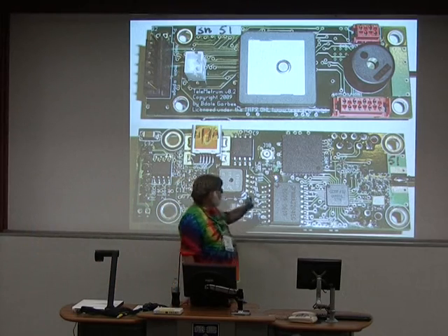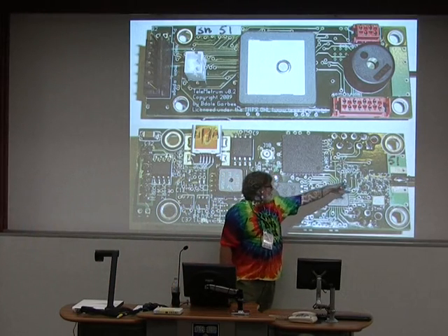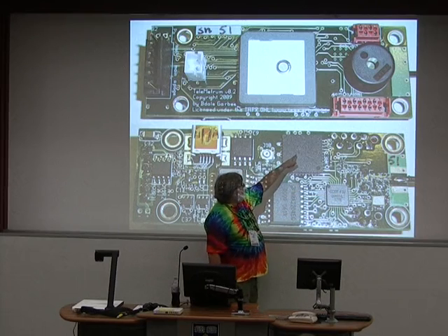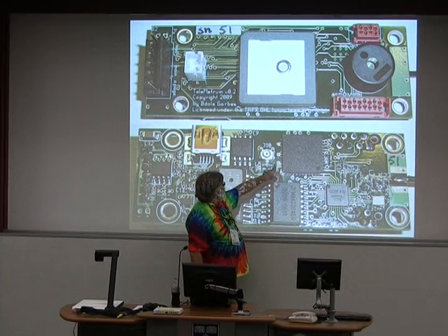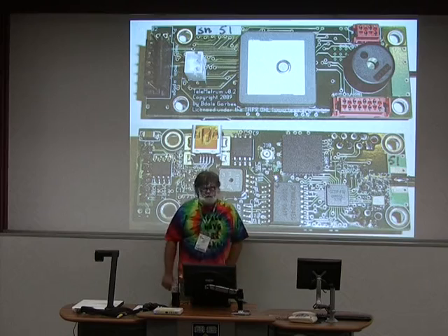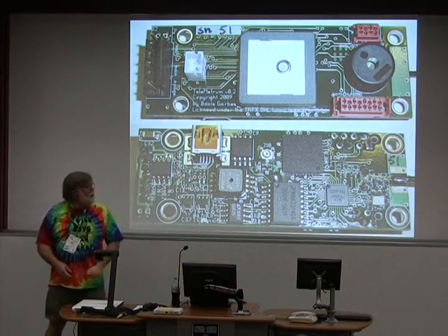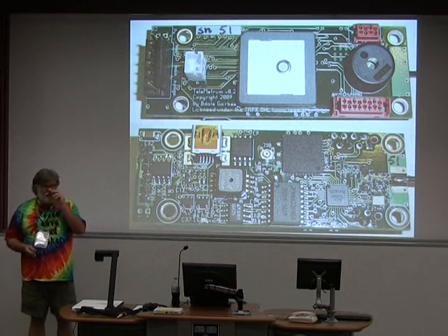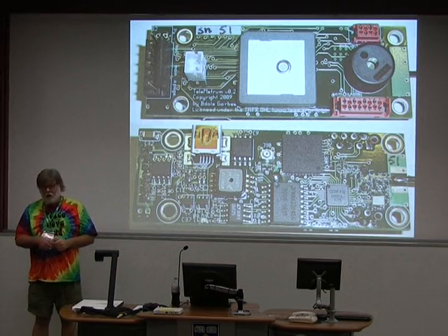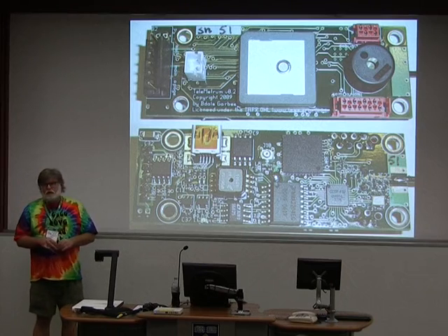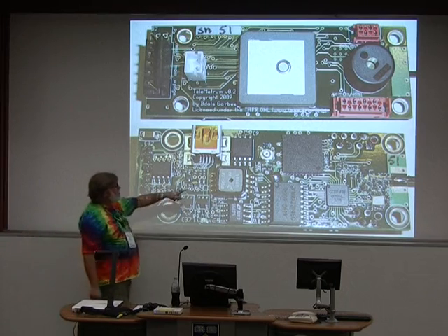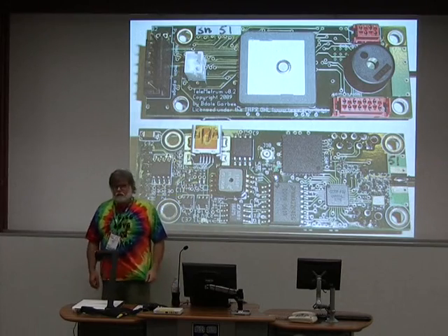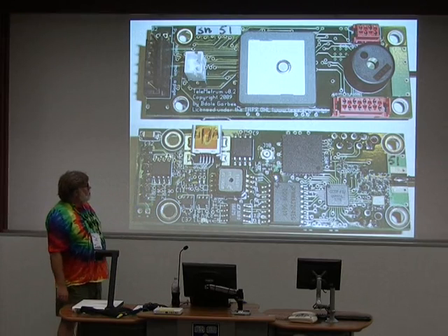And just to show you around a little bit, that's the CC1111 again with its UHF balun filter network. This is the GPS receiver. This is where the patch antenna connection comes through into there. And then this was a connector that I put as a U.FL connector. A lot of GPS modules at that time, a lot of people were using U.FL connectors for connecting the antenna to the receiver. And I don't know why, but I thought it just might be the case that we might want to remote mount a GPS antenna sometimes. Having the connector on the board with a DC bias feed for it and all might be smart. And it turns out that was really important.